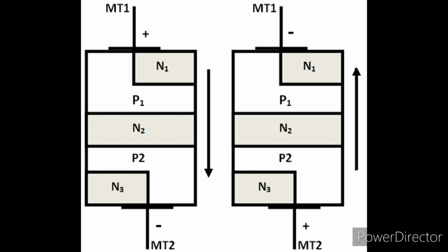This figure shows the construction of the DIAC. It has a 5-layered structure, and you can observe the combination of both positive and negative layers in the layers closer to the terminals. This helps the layer that has the polarity similar to the voltage to get activated, thus helping the DIAC in operation in both the directions. And note that the structure of the DIAC is symmetrical, unlike triac, where triac has 6 doping regions and the structure of the triac is asymmetrical.